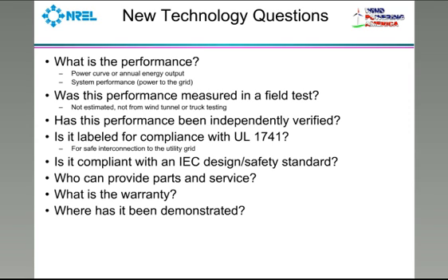Is the turbine labeled for compliance with UL 1741? This is becoming kind of a minimum requirement to be able to connect to the grid, and most turbines have UL compliant inverters. And again, the inverter is UL compliant, not the whole turbine. The advertising sometimes tries to fuzz that issue up a little bit.